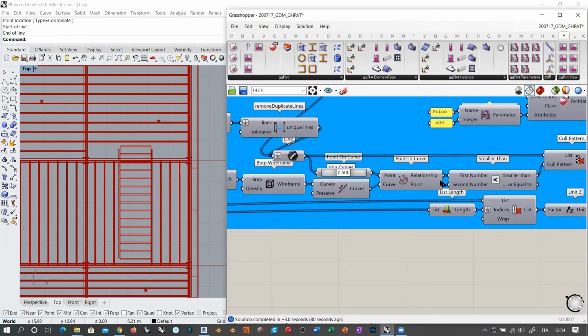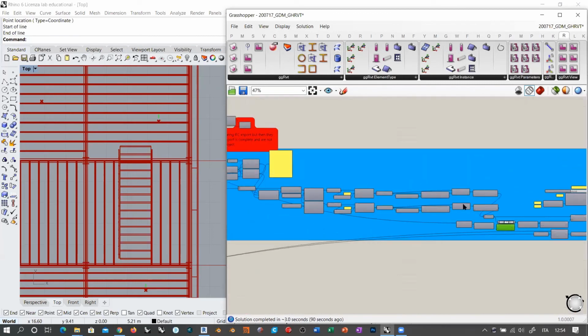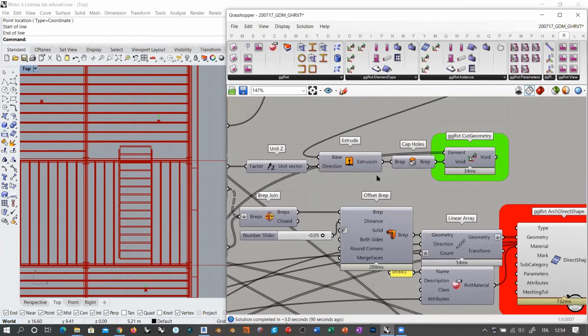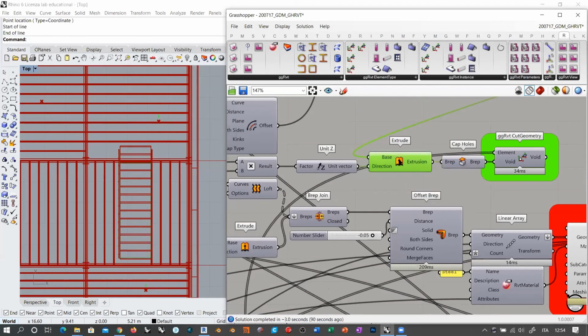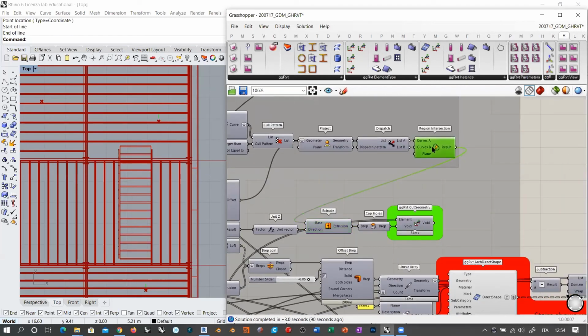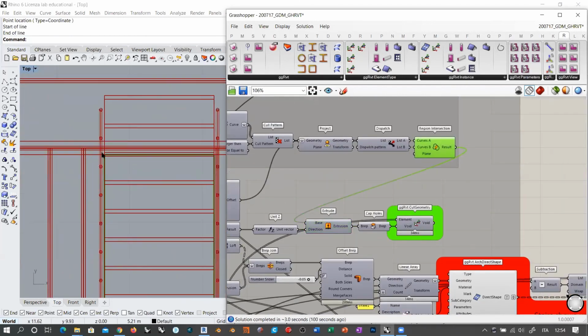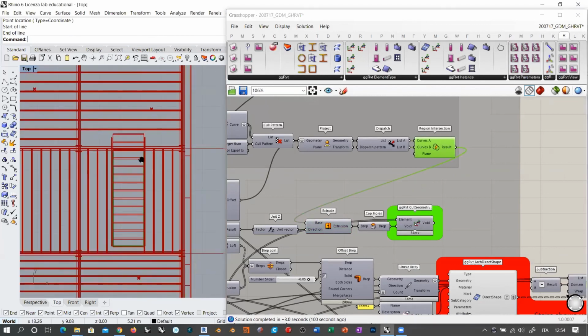This is happening like here, and we are using the footprint of the stair. As you can see, the green area is this one, but instead of using this, I can also take the shaft where it's defined, which is basically this intersection here. You see that now we are reaching only up to this, which is the primary beam, by the way.